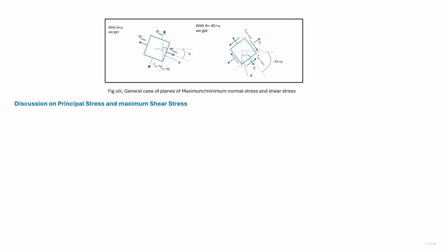We took a simple case, a bar subjected to axial force, and we took up the element in the bar, saw how the stress varies as the element rotates. Some of the trends that we found out are generally applicable. So they are applicable to any point in a structure under any loading. Later on, we will do a thorough investigation into transformation of stresses, where we'll derive formulas that give us an indication of this behavior.